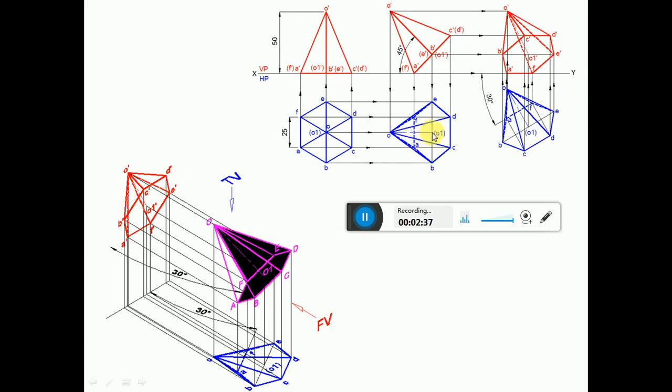Again, by using the compass, you measure the distance from O1 to B and also O1 to E. Both are going to have an equal distance. From O1 you cut an arc on this side to get the point B, and from O1 you cut an arc on this side to get the point E. Then we need to transfer the distance of C and D. This C and D is perpendicular to this AF line. So from A, by using the protractor, you measure an angle of 90 degrees and then draw an inclined perpendicular line here downwards. Similarly, from F you do the same thing.